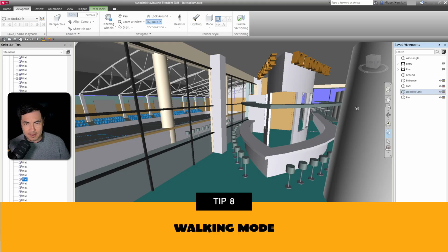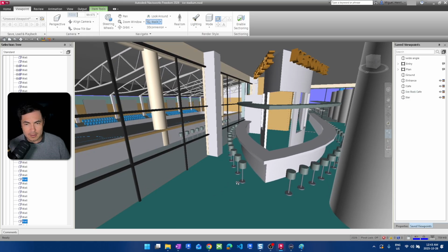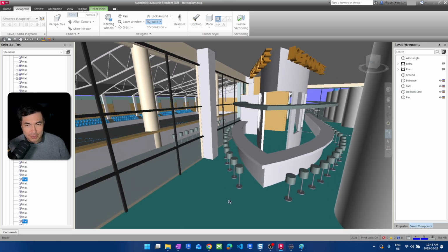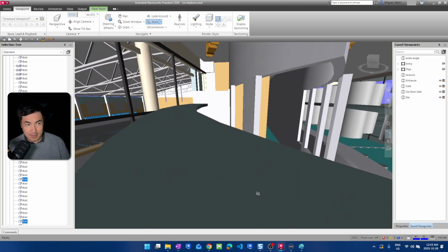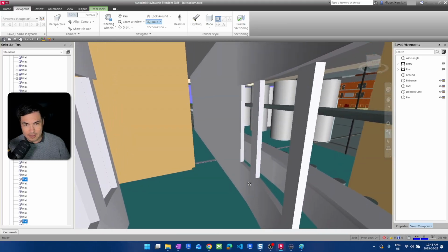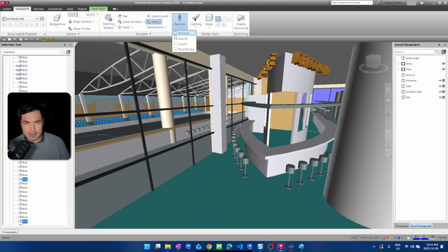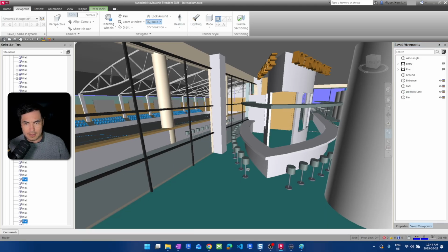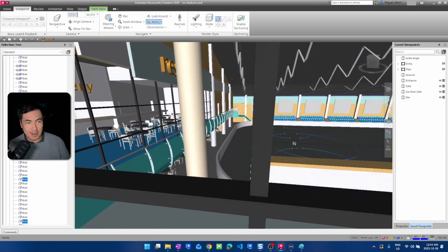And you see, if I go here, I get these icons, or my mouse pointer changes, and that's because I am in the walking mode, so I can walk really slow. So from the bottom, you just drag your left mouse button up just a little bit. If you do it too much, it will go really fast. So you can just walk around. Or let's go back there and let's activate the collision now. Okay, let's see. So if I try, for example, to get out of here, it doesn't allow me to.